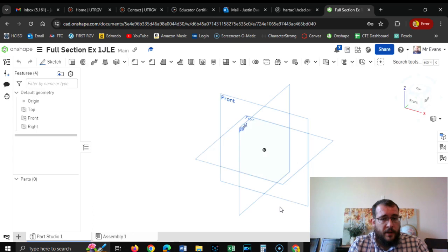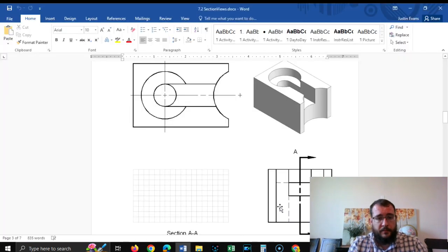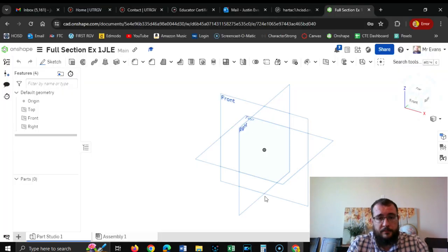Now you're going to want to create a block by extruding it. If you count it, this item is 12 squares across, which ends up being 3 inches. And this is 18 squares across this way, that's width. That ends up being 4.5 inches. And the height of this is 10 squares, which makes it 2.5 inches. So what you need to do is create that.